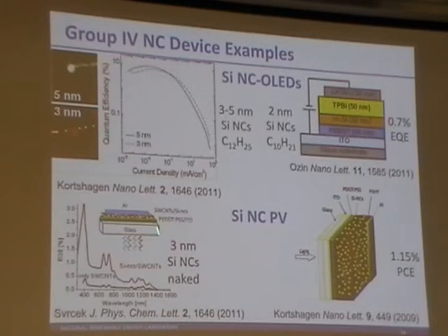There are also some silicon nanocrystal PV out there that's recently come about. The first generation was sort of making a PEDOT:PSS, typical OPV structure where you have the P3HT and then silicon nanocrystals in it. Very similar to what Mark was just talking about with his calculations, where we would be doing calculations about what's going on with energy transfer within that photoactive matrix. In this case, they got about 1% power conversion efficiency from this actual device. I've talked to Uwe and some of his students. This is pretty much where they're stuck.